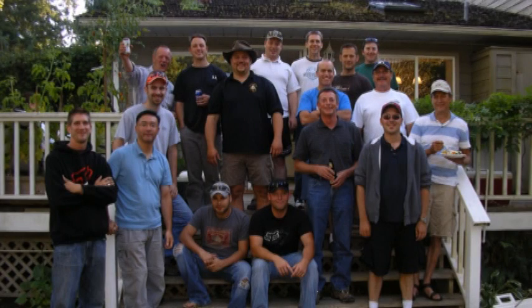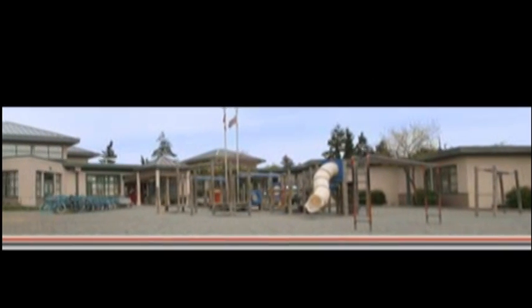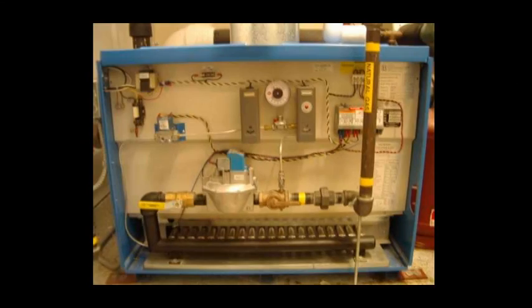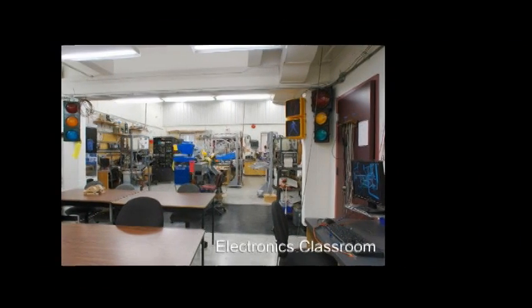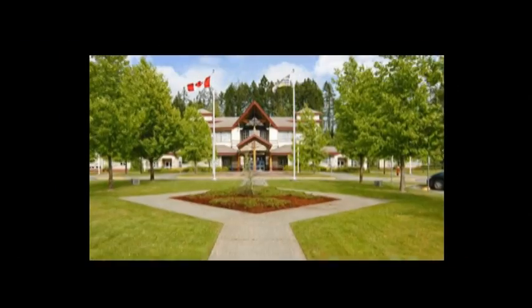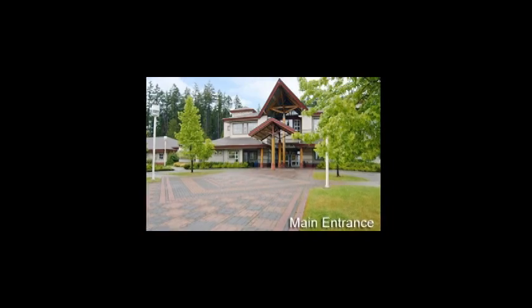Back in November 2007, I was involved in a recommissioning of a small elementary school in Nanaimo school district called Brechin Elementary. The school had weekly schedules starting at 5:30 to 6. We added optimum start and set the weekly schedules to start at 8 and 8:30. This reduced the overall runtime of the equipment and also reduced the amount of fresh air coming into the building during unoccupied times. The school had 5 main fan systems.